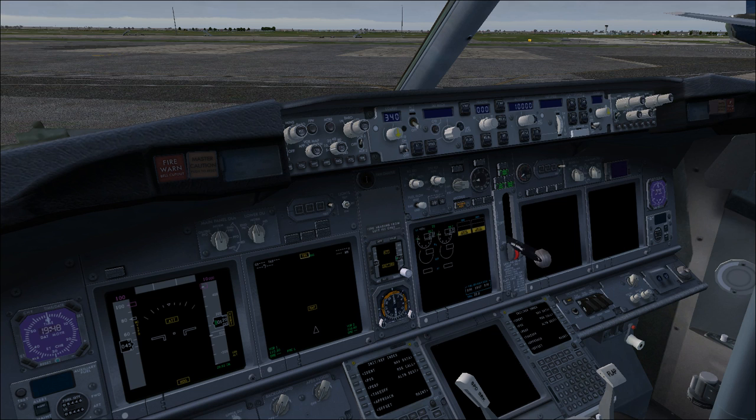The initialization is needed because inside the ISFD there are gears that give us the altitude information. Those gears need to initialize with DC power, and so there is a period of around 3 minutes for startup, in the case of the ISFD first startup. If you are stopped in parking, the initialization progress is only about 30 seconds or so.